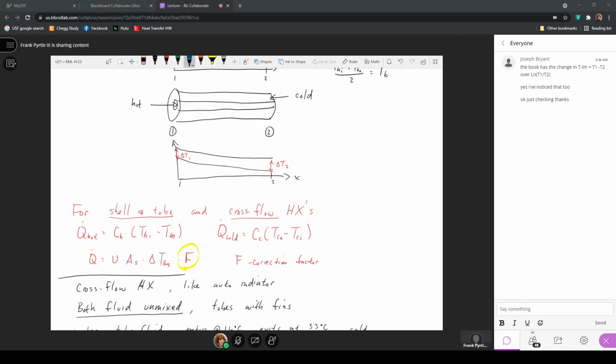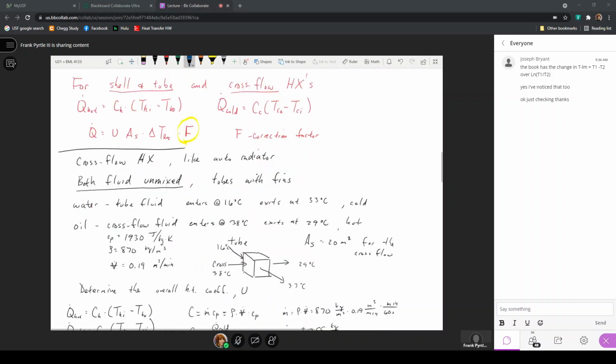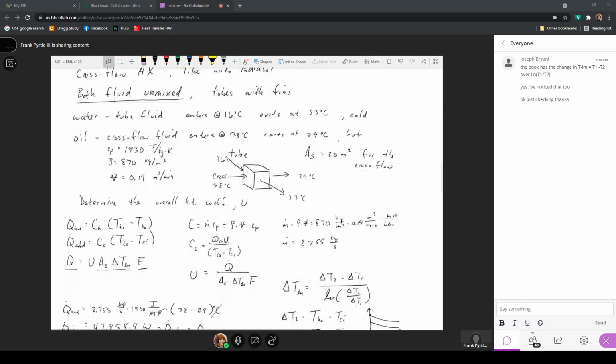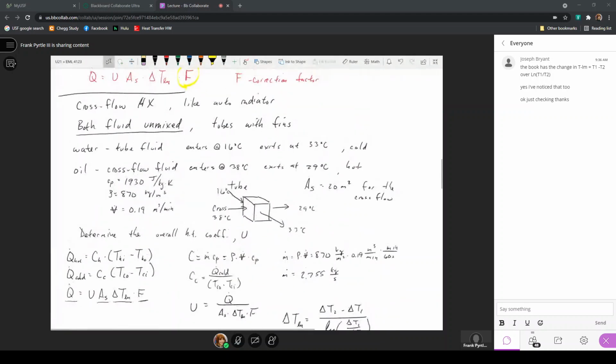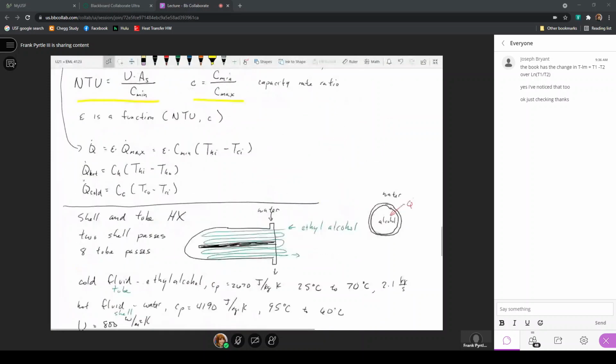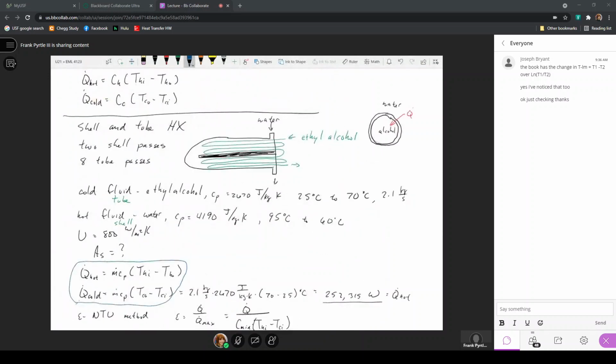that we just calculated, that's based on an expression where we considered that for this problem, the overall heat transfer coefficient, oh no, this was, here we go, back down a little bit here. The overall heat transfer coefficient was given, but in typical cases, if you design a heat exchanger, you know what the surface area is, and you can measure all these other things, the temperatures, the flow rate, etc., and then calculate what that overall heat transfer coefficient is.